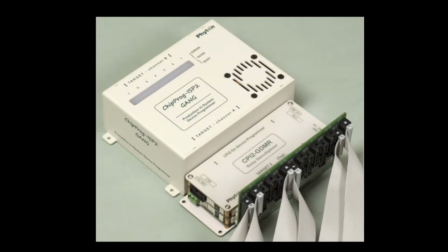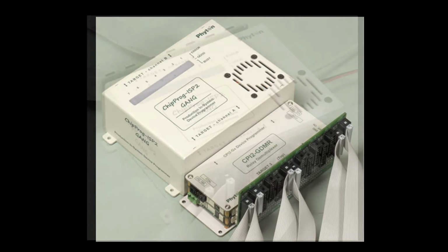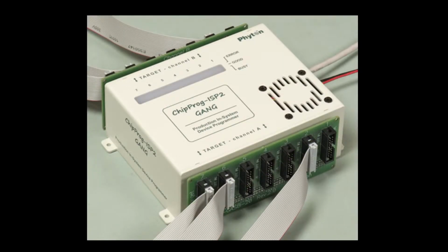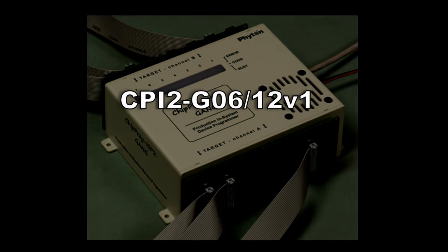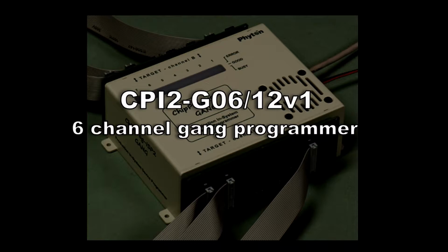So, in general, the programmer enables you to create and run different projects for different programming sites and concurrently flash different types of devices with different data on the same target board. Each module in the programmer has a built-in demultiplexer that can be enabled by an optional license. The CPI2-Gx is a general abbreviation. A particular model part number refers to the number of modules installed in the programmer. For example, the CPI2-G06/12V1 part number refers to a 6-channel gang device programmer.